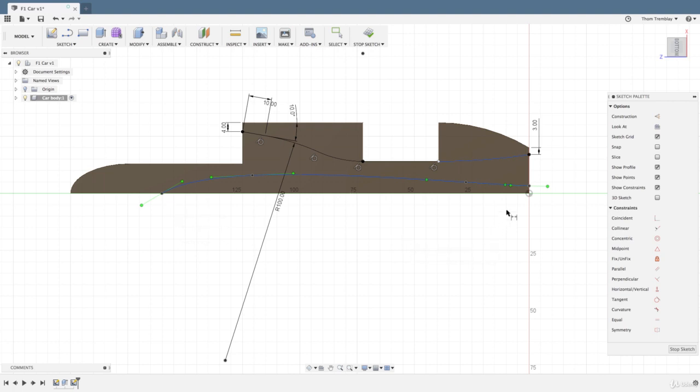For right now, I'll just place some basic dimensions on the points of the spline. First, I'll locate the end point, 2 millimeters off the center line. Then the next point, I'll place it 3 millimeters from the center line at a distance of 30 millimeters from the end. The point that's furthest forward, I'll set at 120 millimeters and 8 millimeters off the center line. And then the last point will be at 170 millimeters.